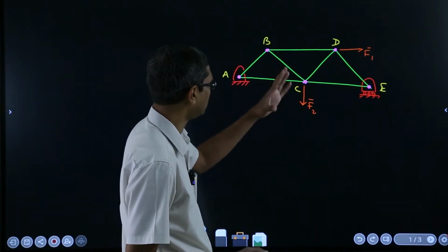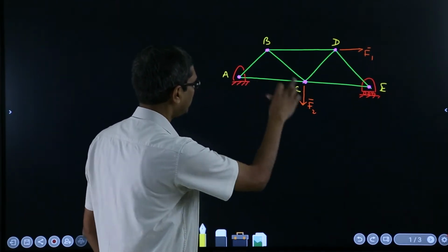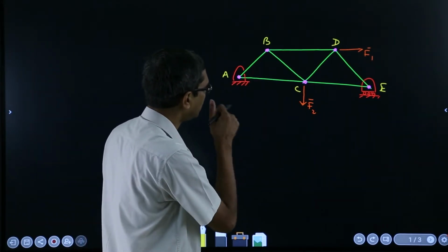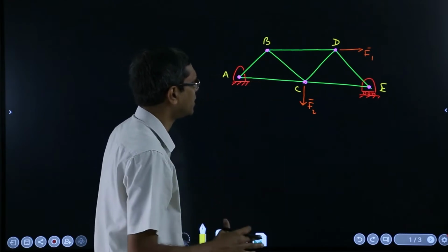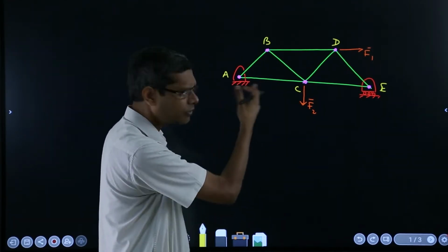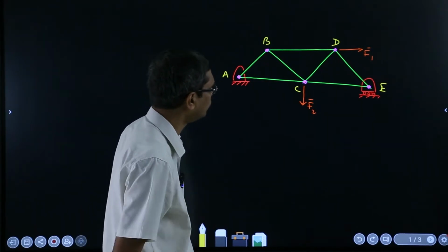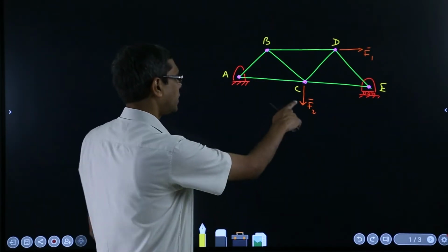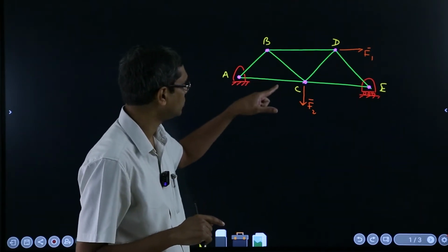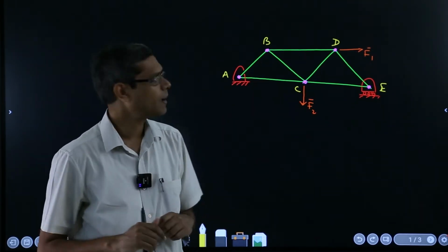And it's a rigid structure, because all of them are triangles, and these triangles are connected through these joints, so it becomes a rigid structure. It doesn't move on its own, or with respect to each other. These links do not move. And one more point we had discussed: the forces act on the joints, not on the members.